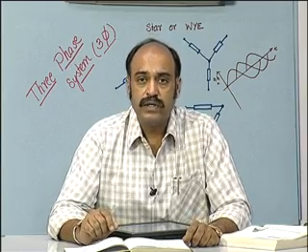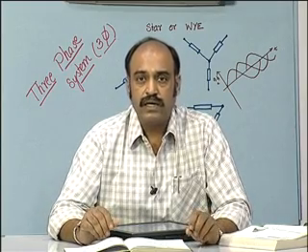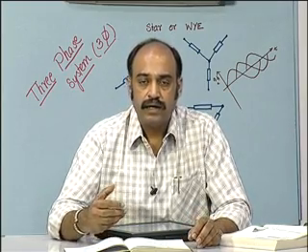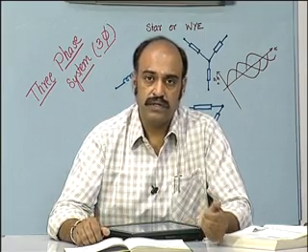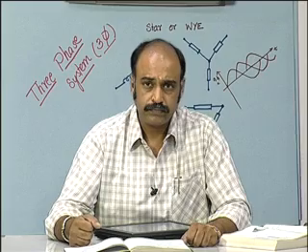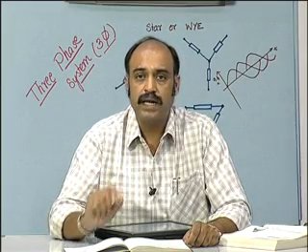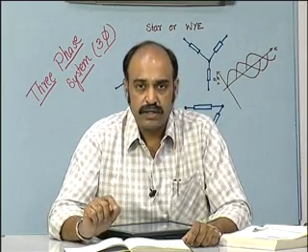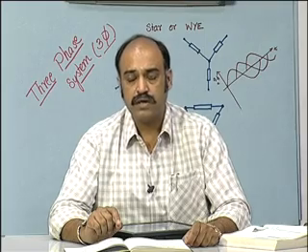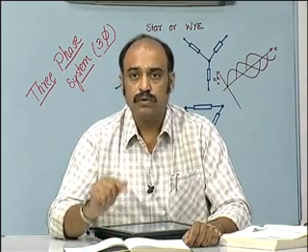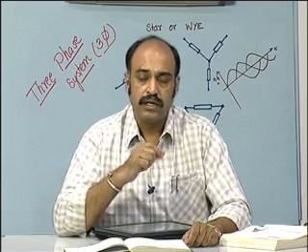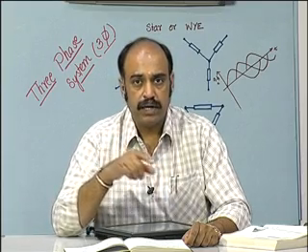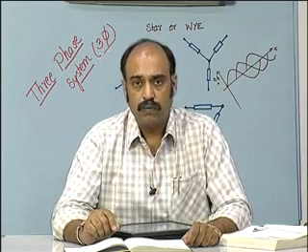As a consequence, we save in copper, since you just need 3 wires to connect a 3-phase source to a 3-phase load. However, if the load is unbalanced, then IA plus IB plus IC is not equal to 0, and therefore we need to provide a return path from the load side to the source side, and that return path is through the neutral wire.